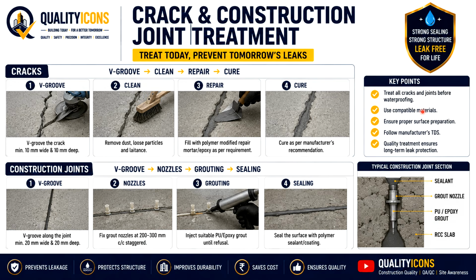Key points. Treat all cracks and joints before waterproofing. Use compatible materials. Ensure proper surface preparation. Follow manufacturer's TDS. Quality treatment ensures long-term leak protection.